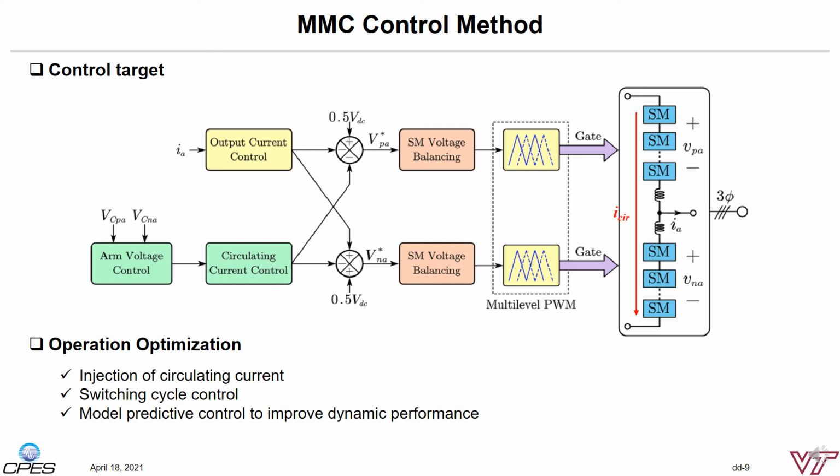Circulation current in each phase leg can be controlled to balance the energies between arms and also between the phase legs. Each submodule capacitor energy can be balanced through the PWM modulation and rotating methods by controlling the bypass time of each submodule. The harmonic current can be injected in the circulation current to control the total energy ripple in the arms, so that the voltage ripple of the MMC submodule can be controlled and even reduced to some extent.